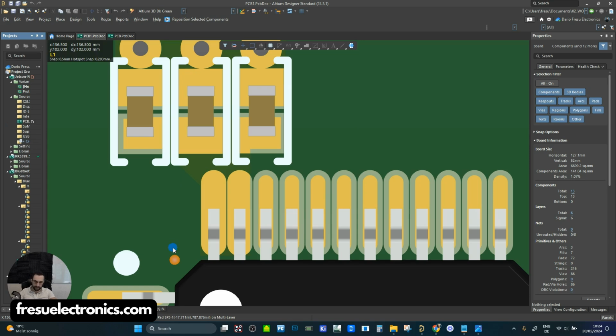So you see, this is already one of the connections that we have between the EMI performance, signal integrity performance, and the layout itself. Okay, but if we have this inductance, then we need to take into account the resonant frequency of the capacitor that we are selecting, and how the inductance of the package, the traces and the pins will have an impact on the resonant frequency of this part of the power delivery network.